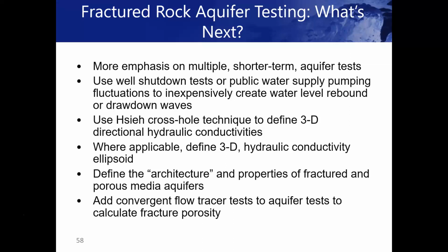They did add an additional comment. Okay. Plus dewatering lower yield fracture or bedding zone intervals. This is more applicable to production wells in bedrock settings. Yeah, that's in fractured rock with a well that is screened across most of the aquifer. So a long screened well,